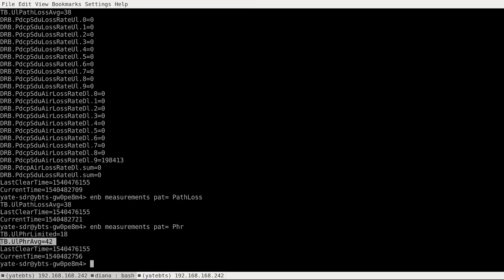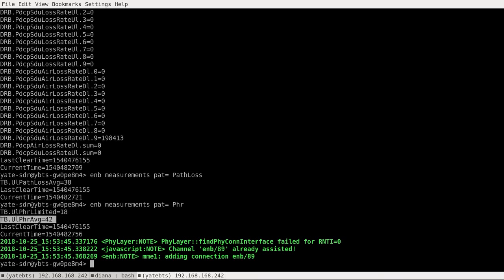If this power headroom number were closer to 0, that would tell you that the transmit power in the unit is being pushed close to the limit of the amplifiers. If that number hits 0 or becomes negative, that tells you that the device under test is transmitting at its maximum power. And you can use this power headroom number if you need to make a maximum power test. You can use it to verify that you actually are at maximum power.